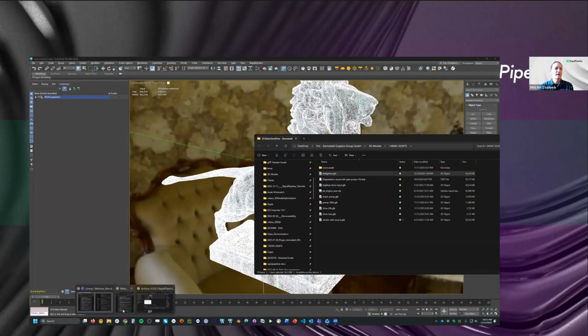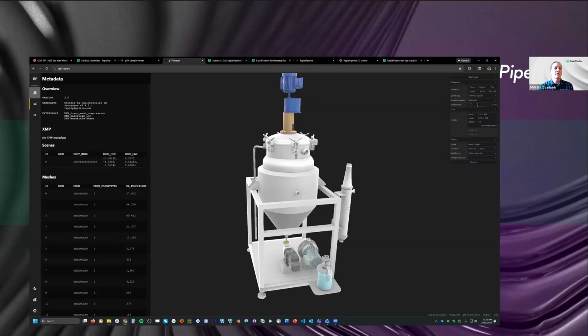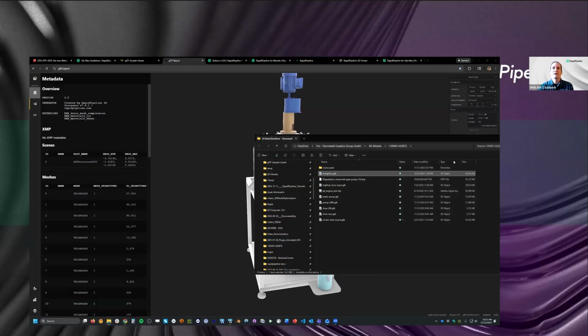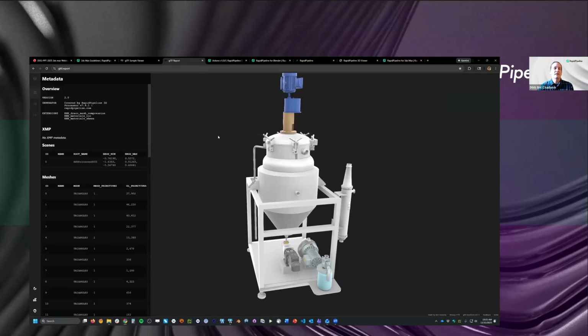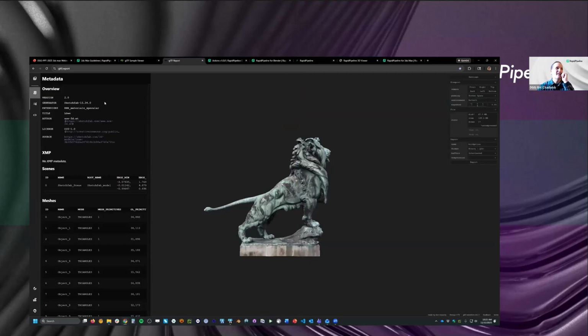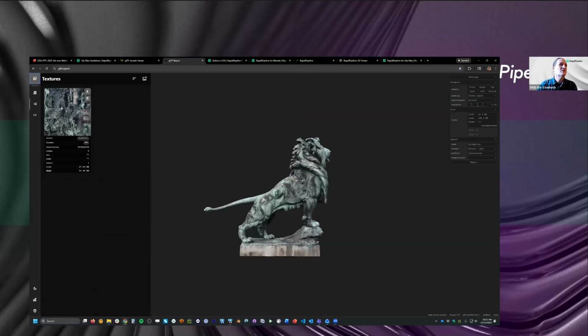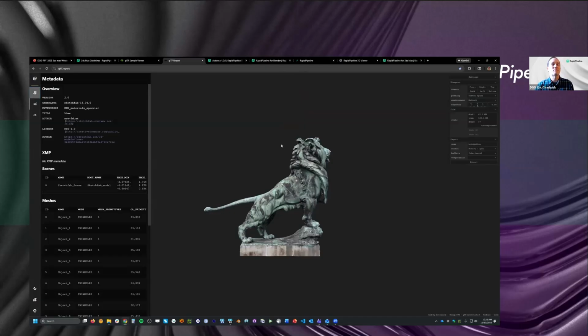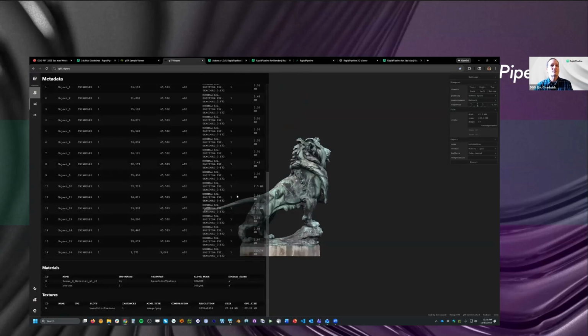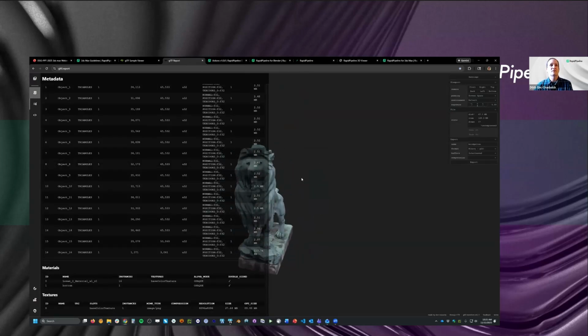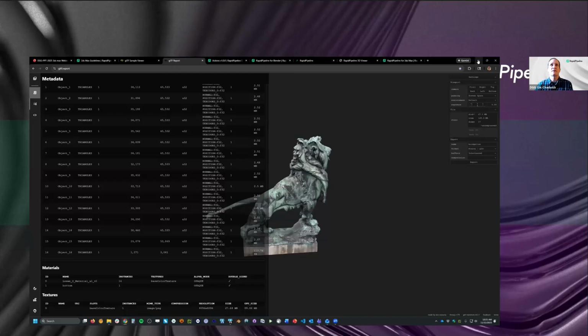Let's take a look at it in GLTF report and see how big those textures are. Let me pull it in. It's a 65 meg file. Let's see. It's got one 4K texture. So the texture really isn't the problem, although it is a PNG file, which makes it pretty big. The problem is it's got way too many parts and way too many triangles. And so it's a pretty inefficient file as far as web viewing goes. It just takes too long for people to download.